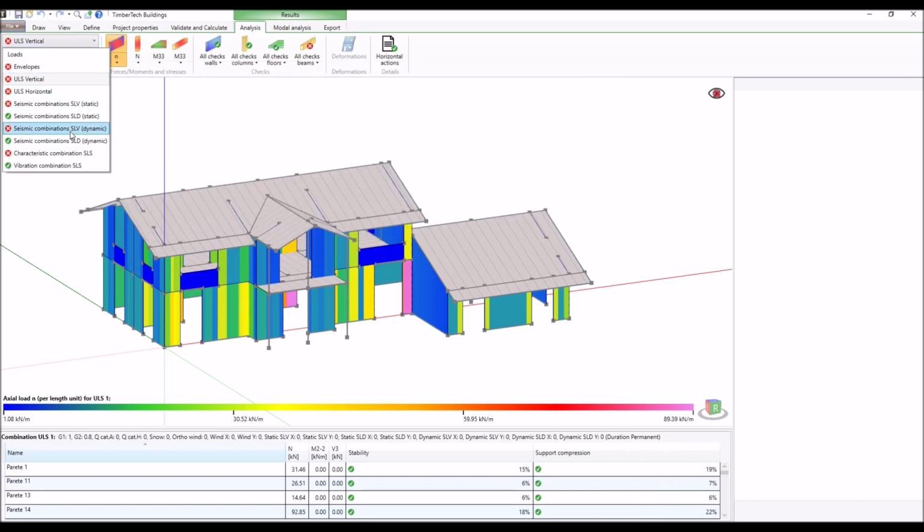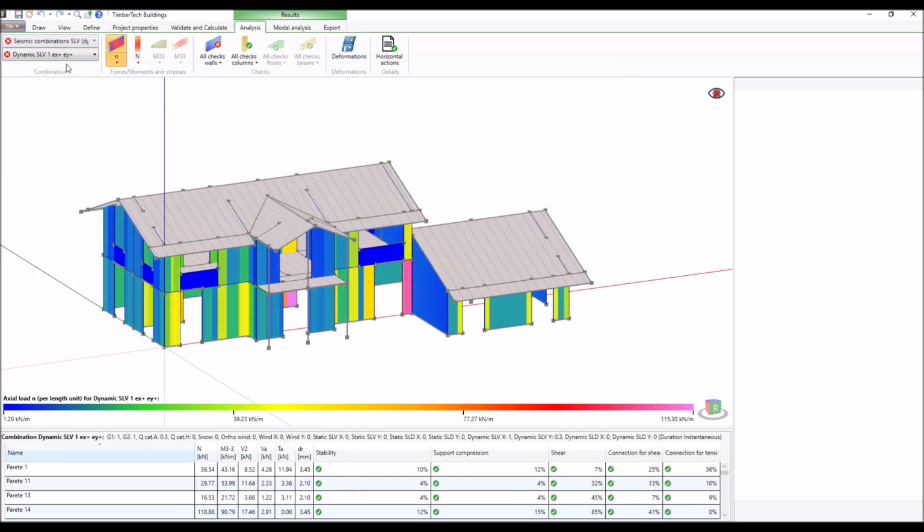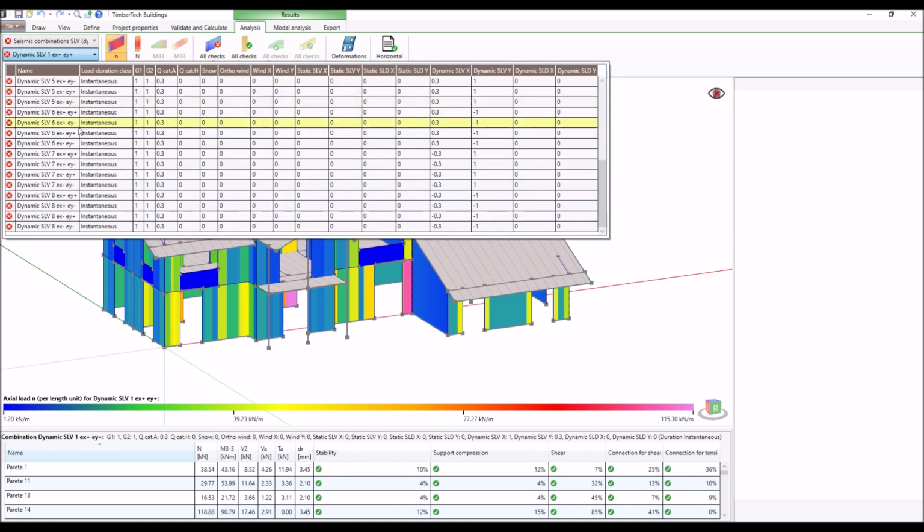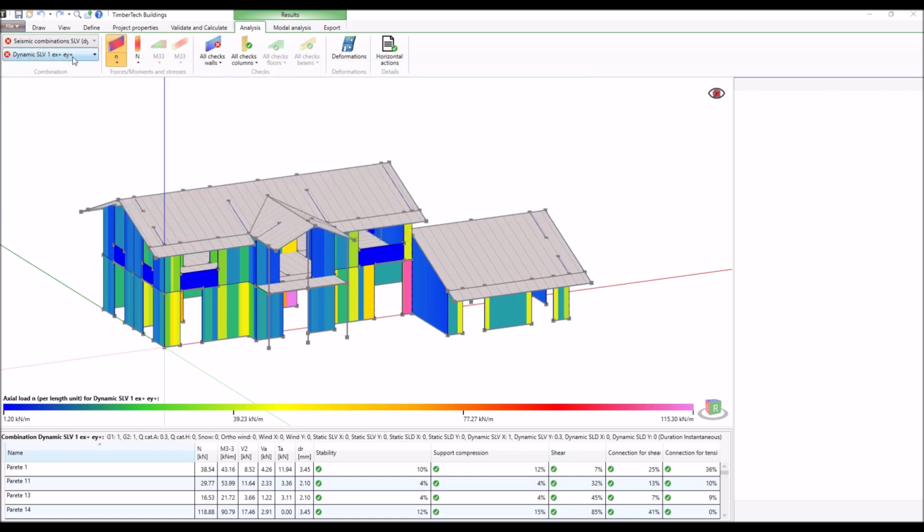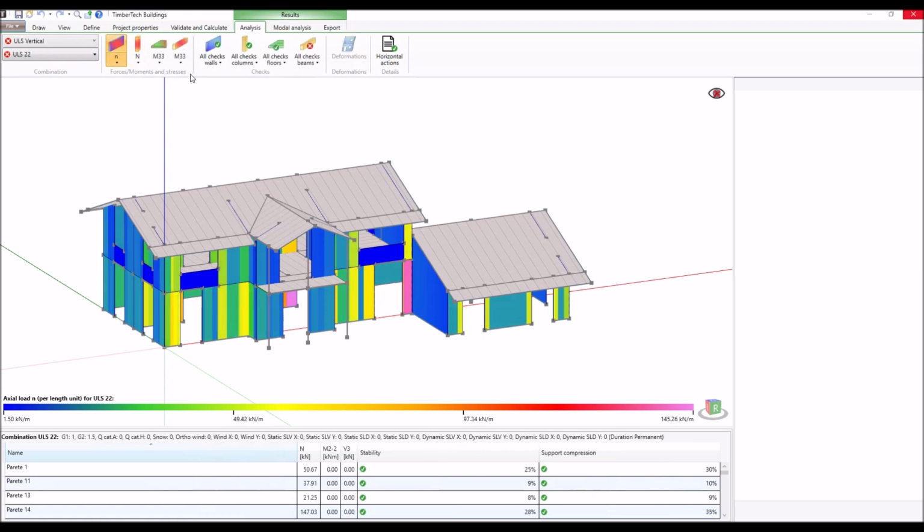For example, observe the load combinations at the ultimate limit state, or the combinations for the limit state for the safeguard of human life, that include the seismic loads. The stresses present inside the structural elements can be recalled and represented on the screen by means of the buttons that are located at the top in the central part of the menu.